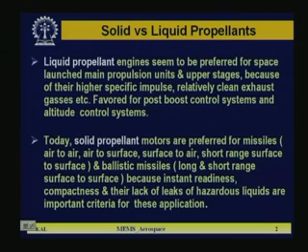On the other hand, solid propellant motors are preferred for missiles: air to air, air to surface, surface to air, short range surface to surface. For this kind of missile, solid propellants are sometimes favored. They are also preferred for ballistic missiles, long and short range surface to surface, because instant readiness, compactness and their lack of leaks of hazardous liquids are important criteria for this application.